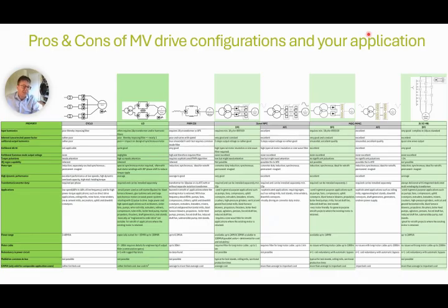We refer to a 4-quadrant operation when the power flow from the machine towards the drive and the grid is consistent, and regenerative operation is required. You can also operate in the 4 quadrants with a drive using a chopper and a brake resistor, but when we refer to a 4-quadrant drive, we actually mean a regenerative drive that can send energy back to the grid.